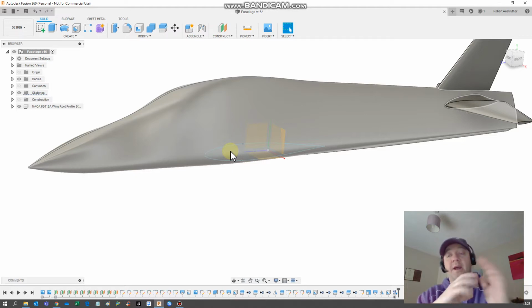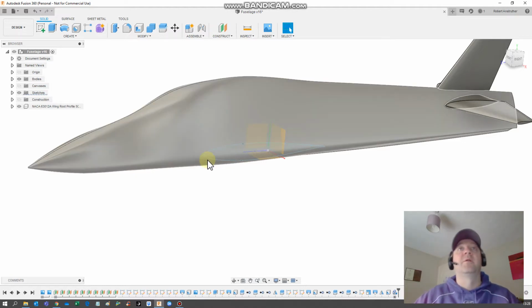So in any place where you're designing something like this for a composite, you need to think about how you're going to make the mold and how you're going to take it apart. This is very relevant for everything you do. Having smooth and filleted surfaces will help a lot. 90-degree angles are not good, and straight surfaces aren't particularly good either. You're always better off having a tiny bit of angle on it to help that separation process when you get to molding and creating parts.